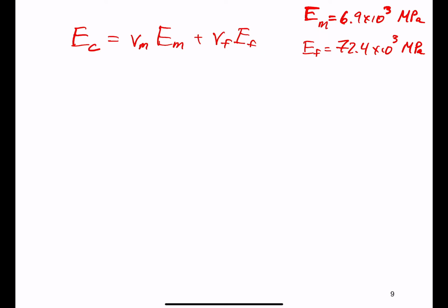We also know that the polyester was reinforced with 60 volume percent E-glass. So that is to say VF is equal to 0.6, given that it must lie somewhere between 0 and 1. This also tells us that VM must equal 0.4, 1 minus that 0.6 value.